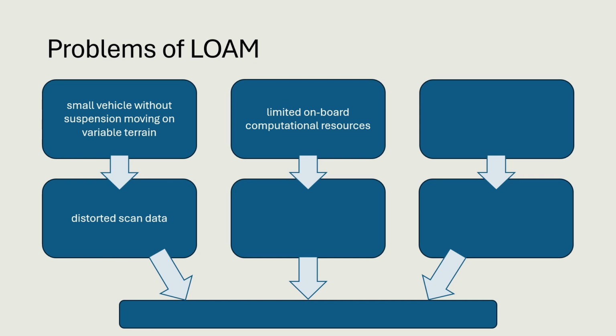Simultaneously, it has to process the captured data in real time to work reliably and produce the estimations for the current pose. As a consequence, the number of processed points has to be chosen with respect to the available resources. The amount of data therefore is reduced by considering only a limited number of points for pose estimation. This unavoidably leads to inaccuracies and uncertainties in pose estimation.